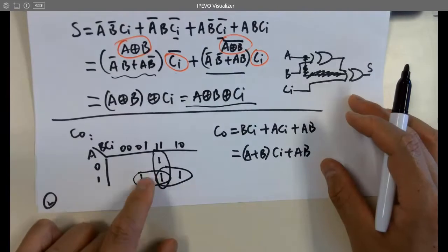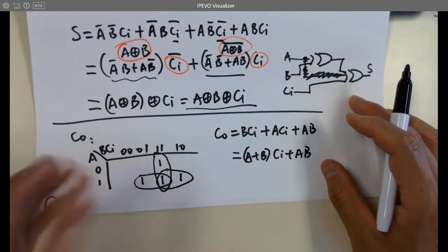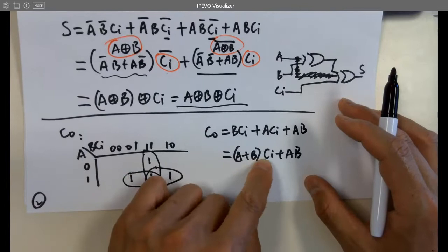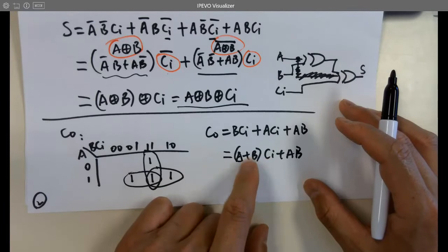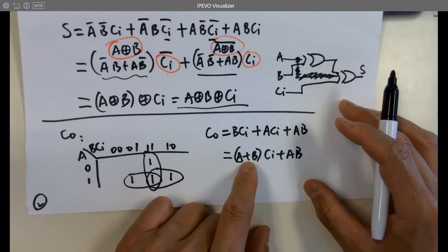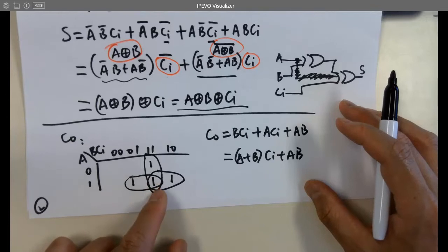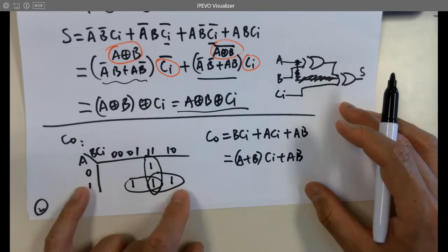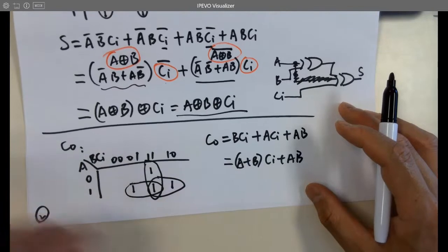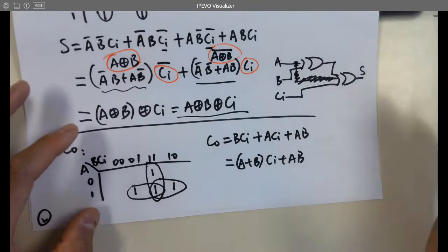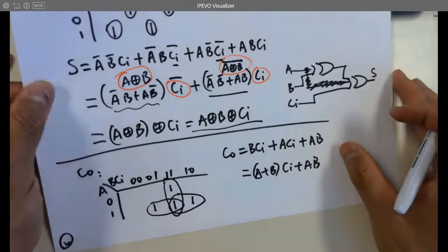Follow this one. You can group in different ways. Group these two and leave this one single, or just group these two, whatever. There are probably A XOR B forms sometimes in some other forms, but I can tell you it's not an ideal way to do it. So this is a lot better than that. Static hazard if you leave one out, right? That's why I don't want to do it. That's why I want to group all of them together. So this is a lot better choice. But still, from the textbooks, a lot of people are still using A XOR B. Why? It's making no sense.